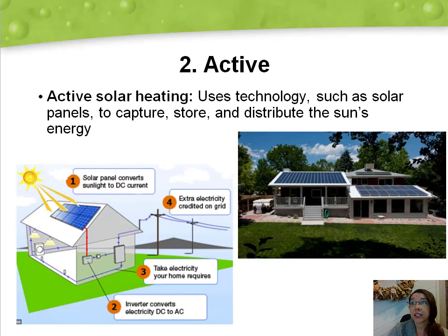So how exactly does the flat plate solar collector work? Like we said, in the flat plate solar collector, as seen in this image, sunlight heats this metal plate, and then fluid is running through tubing within it. And that fluid absorbs heat from the metal plate, and then a pump is able to circulate the heated fluid through the building.